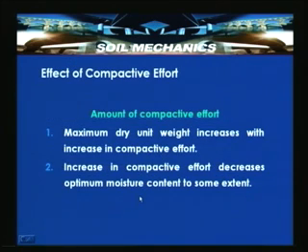Let us look into another factor, which is called the effect of compactive effort. This can also be discussed as the amount of compactive effort which is applied. It is not that when you apply more and more blows to the soil, the soil particles will be compacted to the maximum possible densities. There is a certain optimum compactive effort that is required to be applied to the soils. By applying more, there is no use; we will be creating an instability in the soil matrix.